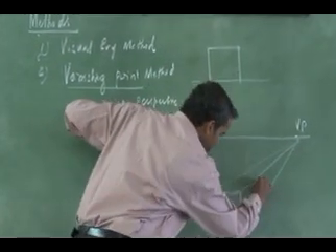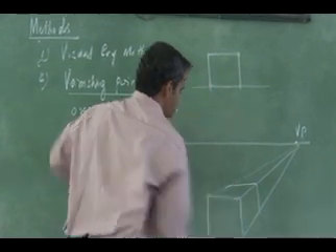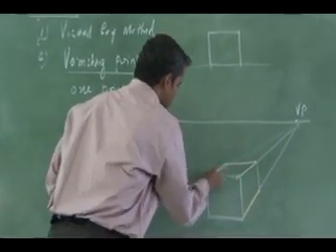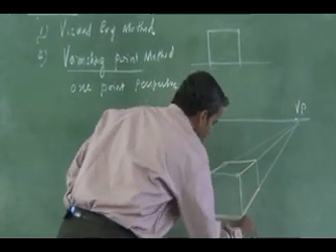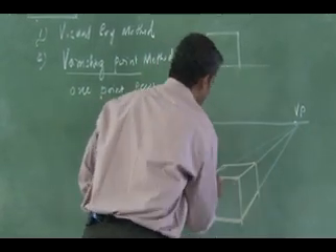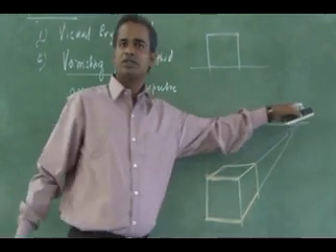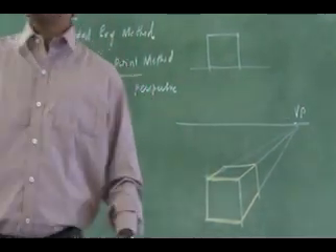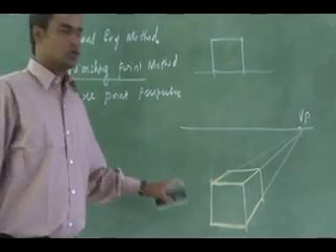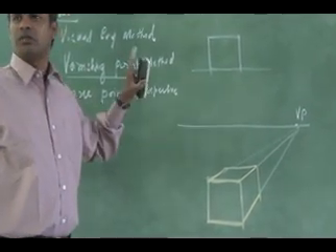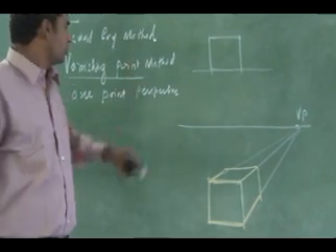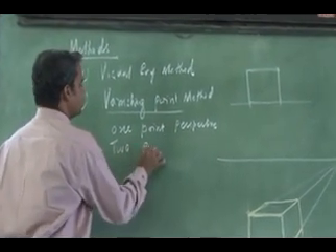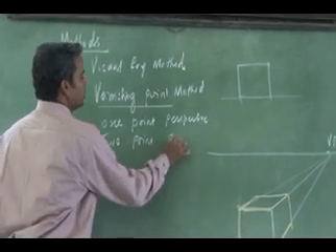Right, if I draw it, this is going to be my perspective. You see, all the faces get vanished to a single point. So this is the perspective view. It will give some appearance, right? So it's a single vanishing point method. Is it clear? So similarly, I have two vanishing points, 2 point perspective.